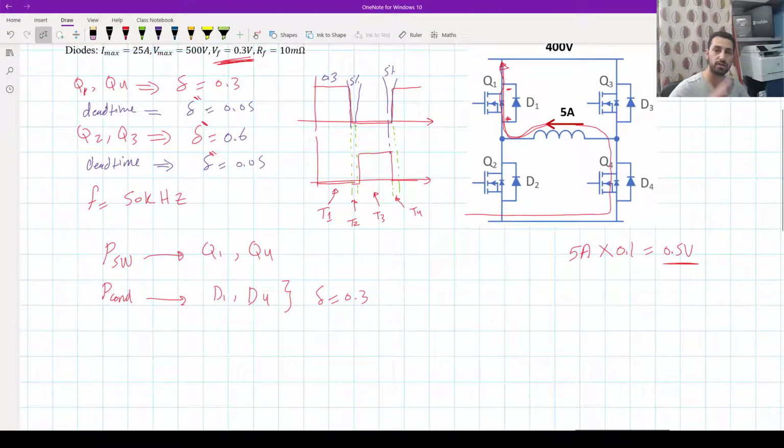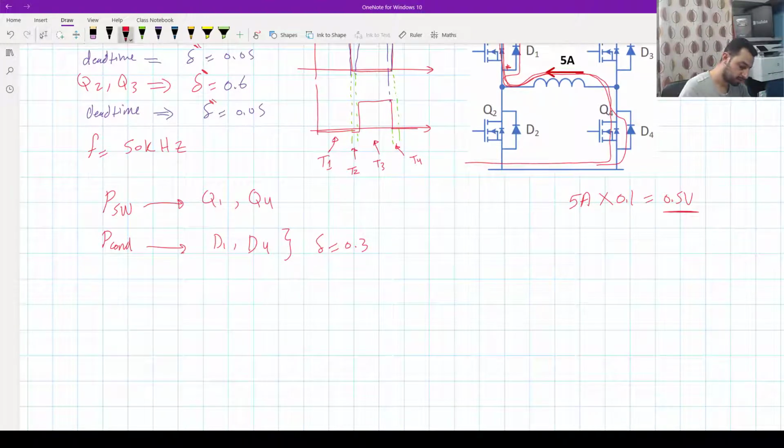During the dead time, we are switching off all the transistors. That means Q1 and Q4 will be off. But again, the inductive load continues pushing that current. And now the current, I think, has already established its route to go through that diode, okay? From the first 30%, it's already going through the diode. And when you provide the dead time, it will keep going through the same diode. So we have D1 and D4 will work during the 0.3, okay, and also during the first